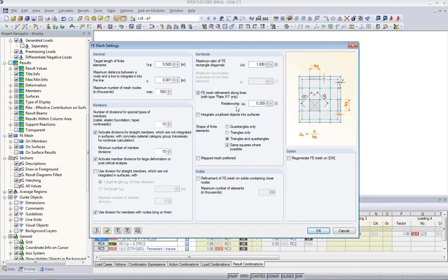You can control it by this parameter here. This is a good idea because where I have the linear supports, and mostly they are at the edges, I have large gradients of stresses, and especially for shear forces, it will somewhat condense those extreme values closer to the edge, inside of the wall. And they will not be disturbing the design later on in RF-CONCRETE Surfaces so much.